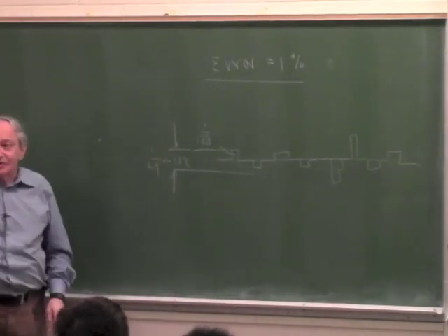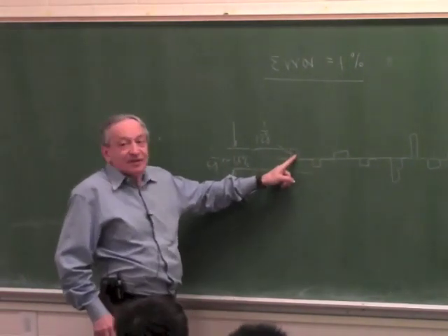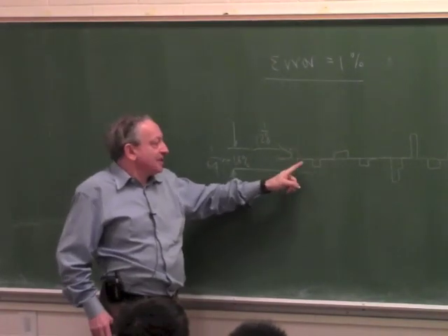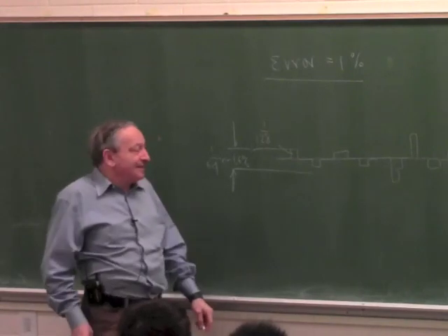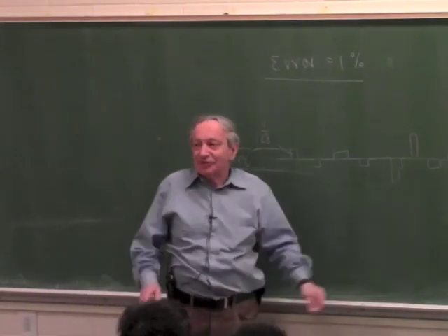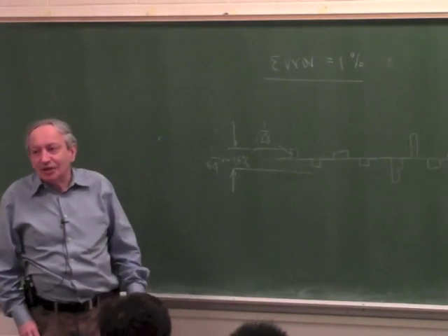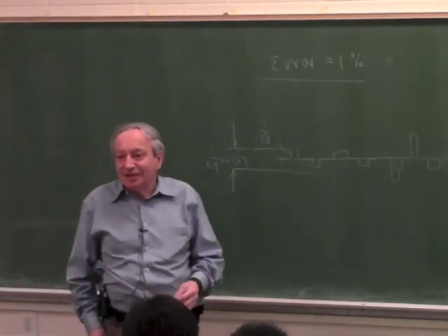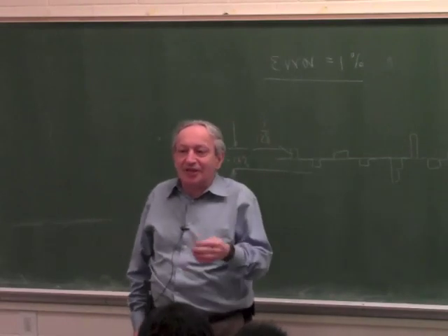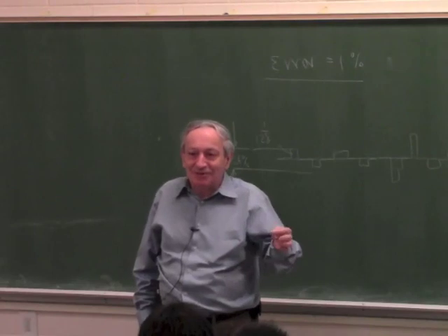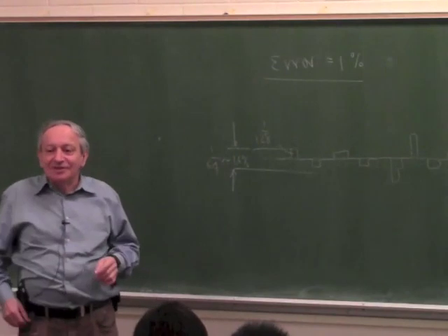Okay? So for sure you need 8 bits, because in 8 bits, this is 1 over 256, say 0.4%, so the peak-to-peak error will be 0.8%. But in reality, it will do this many times. So if you absolutely really need a servo to hold the total error to 1%, probably 8 bits are very marginal. You would go with a 10-bit system or a 9-bit system. 9 doesn't exist. Most of these A to Ds and systems go 8-bit, 10-bit, 12-bit, 14-bit, 16-bit. So it's kind of not a standard number, a 9-bit A to D or system.